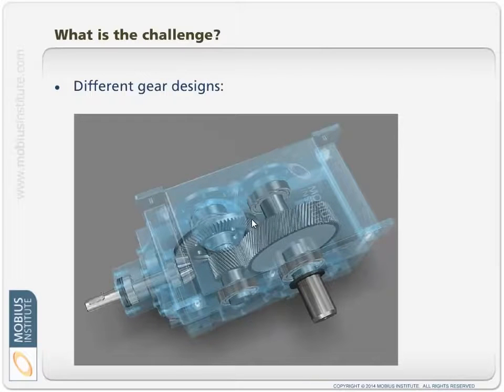But of course you've got to look at what mounting points you have available, how thick is the metal, are you going to be dealing with resonance. Some people actually use the potential of resonance to help them, because they figure, well, if the case resonates, that's going to amplify vibration. That's an interesting approach, as long as you've got good repeatability and a good transmission path from these forces through to the point where you take the measurements.